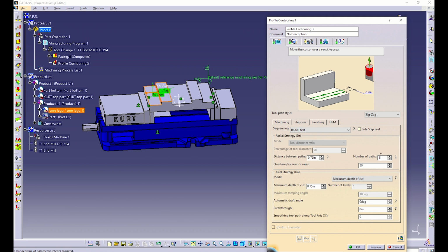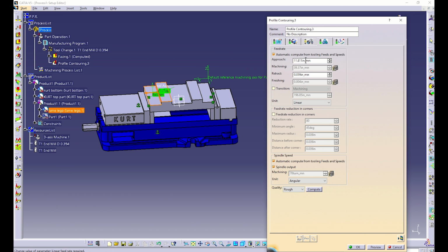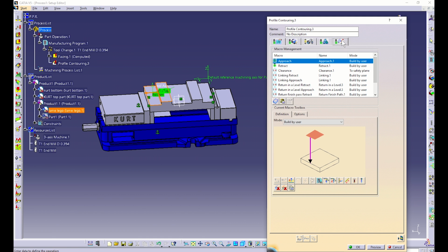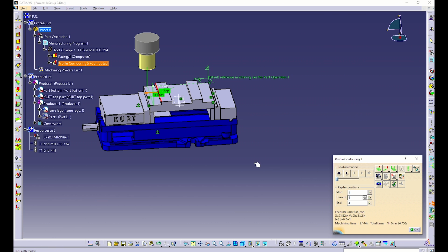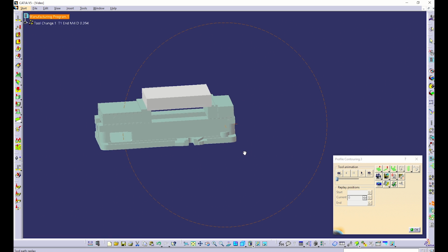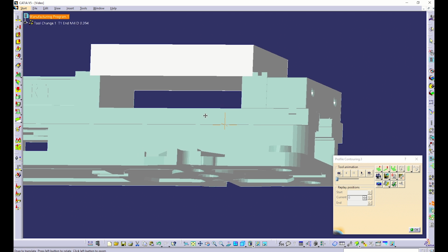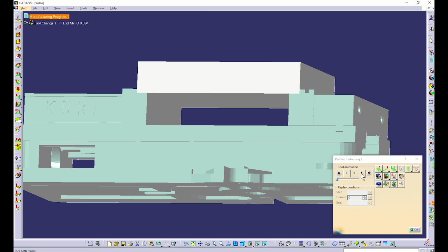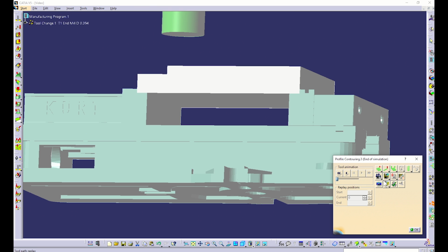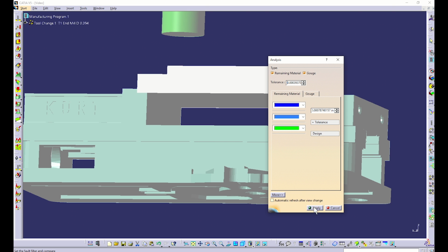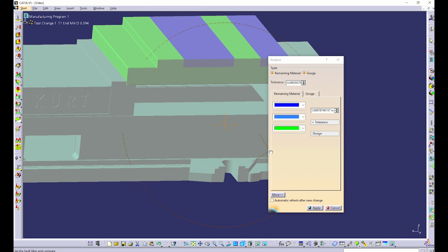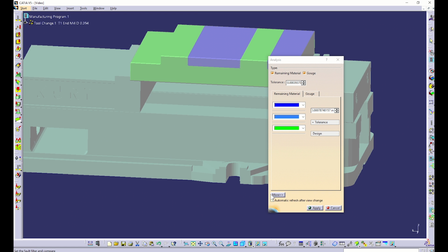This is not a very complex part. But what I was saying earlier was making sure, because some parts will be more complicated. The stock for this, we made it to where it was perfect, so we won't have to flip it around, but sometimes you'll need to make two separate machining process parts. You might need to do one like what we have here, and then flip the part over and face the bottom so it's in the correct dimensions, especially with the projects that you guys do in class.